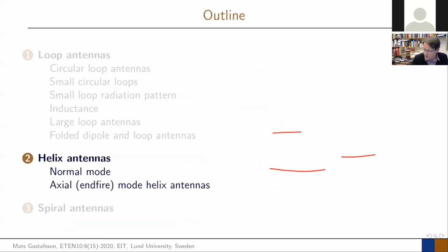So that is in some ways an idea of what's happening with this type of loop antennas. And the loop antennas, as I mentioned, are mainly used, I would say, as a receiving antenna if they are small. Larger loop antennas can be used in some cases, but they're really not seen as a loop anymore. They're really like a folded dipole or 2 dipoles that are a little bit separated. And there are applications for them.